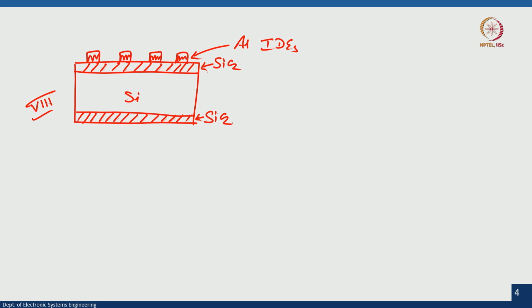Now, let us take an example of PECVD and its advantage. I want to now grow silicon dioxide on this particular wafer. If I go for any other CVD techniques, then you know that the temperature is greater than 700 degree centigrade. What I want is, I will show it here, this is what I want.